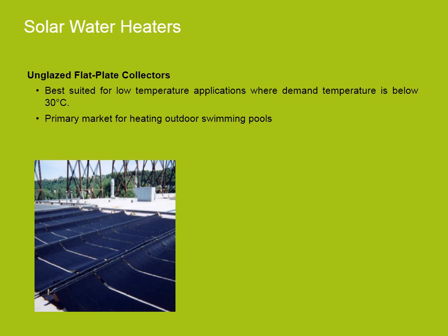Unglazed flat plate collectors are best suited for low temperature applications where the demand temperature is below 30 degrees Celsius because they are not insulated. By far, the primary market is for heating outdoor swimming pools, but other markets exist including heating seasonal indoor swimming pools, preheating water for car washes, and heating water used in fish farming operations.